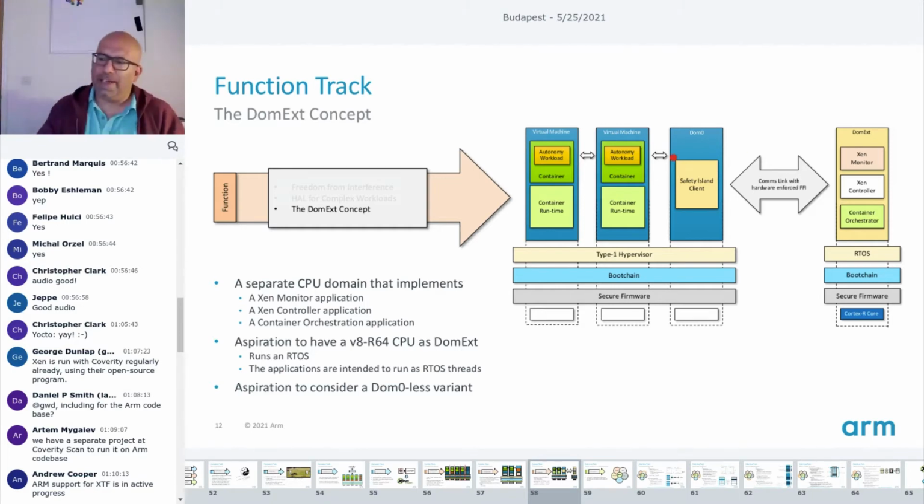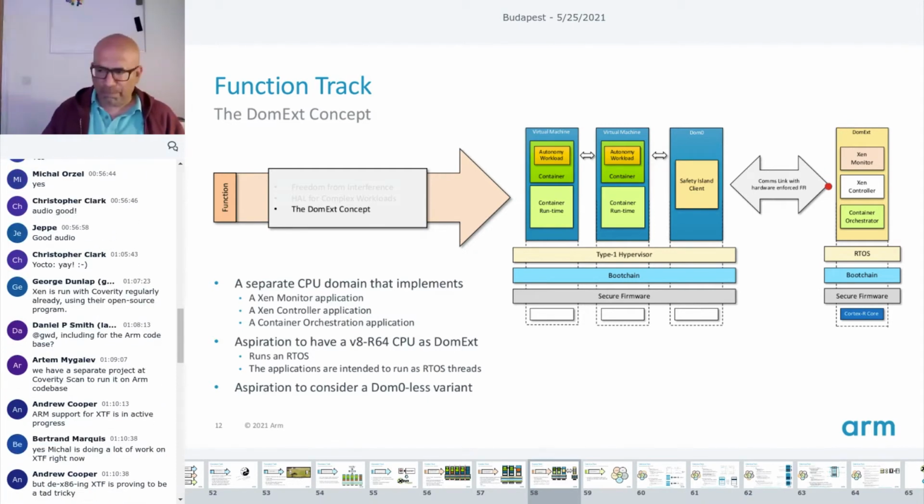Yeah, right. So what this really is about is that in highly safety sensitive applications, you want to separate the primary compute, the stuff that runs your vehicle autonomy control pipeline algorithms, from this external entity which is implemented in hardware and software to be of very high quality, right? What I mean from a safety standpoint, right? And what is its role? Its role is actually to deploy work on the primary compute. Its role is to monitor it. Its role is to control it. And control also means things like updates and stuff like that, right? So this entity by the side, the industry uses different names for it, but I think what everyone wants to say is a safety island in that sense.